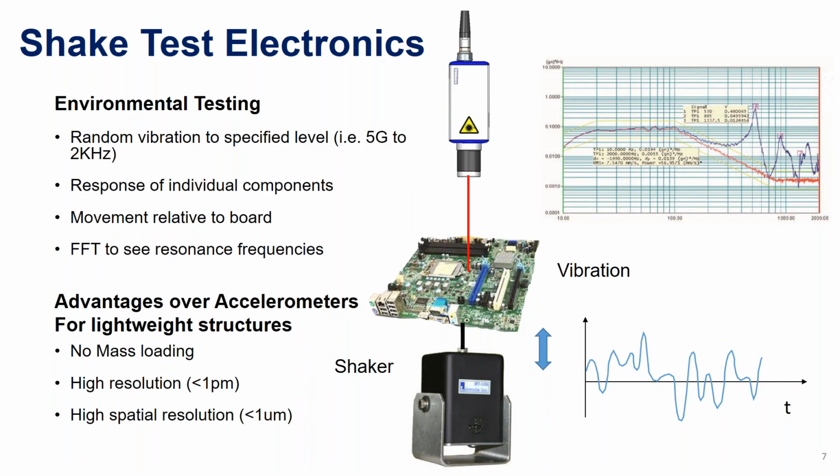A typical test for electronics, a lot of times we do shake tests. The idea is that you want to measure the vibration of components on a circuit board. A starting point for that is to provide a shake test. If you want to do modal analysis, or you want to just see the response of an individual component on a circuit board to a shake environment, you can put it on a shaker. You can run a specified